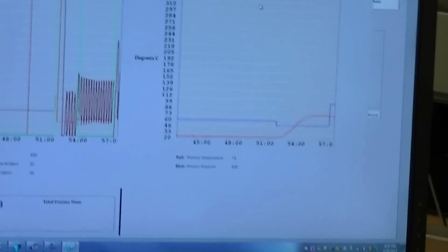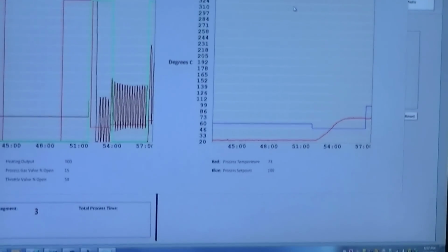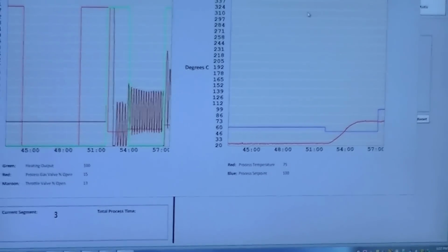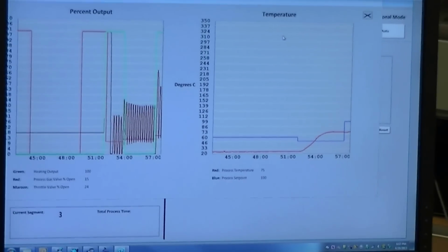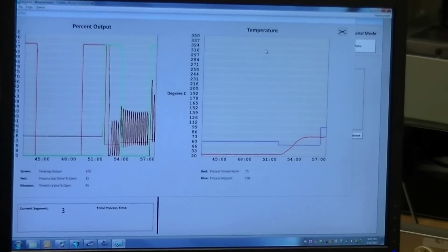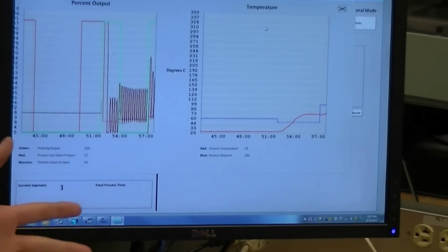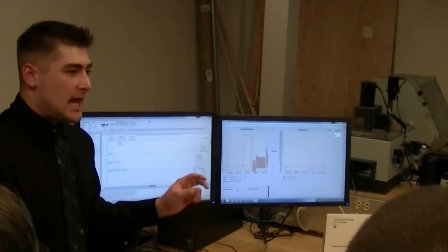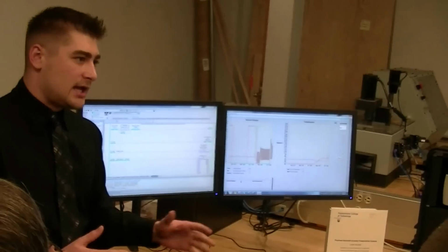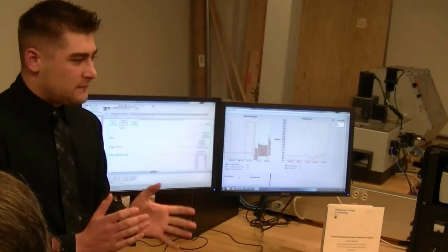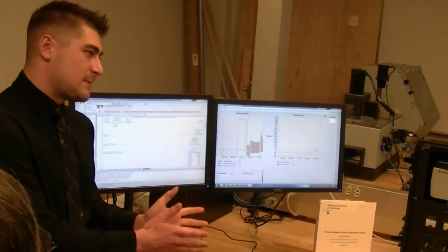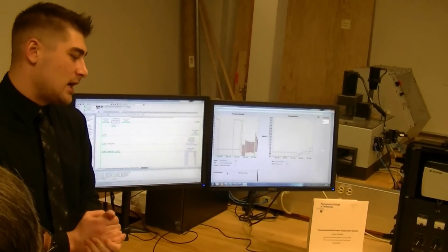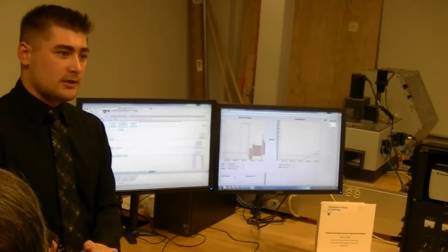But again, this is a great tool, especially in industry, to see, okay, if you set this system and say it's running for a couple hours on end, well, you might not be there when it fails. Having a historical trender, you can go back and find out, okay, when did this segment fail? And why did it fail? You can look at your process variables and find out, well, when I was away, during the night shift at 2 o'clock in the morning in segment X, I found out that my heaters stopped getting a receive signal. So then you have a means of narrowing your troubleshooting process to one specific segment. It's a great kind of feedback for the user to find out exactly where they can adjust themselves and find out where they can at least start to tackle the problem.